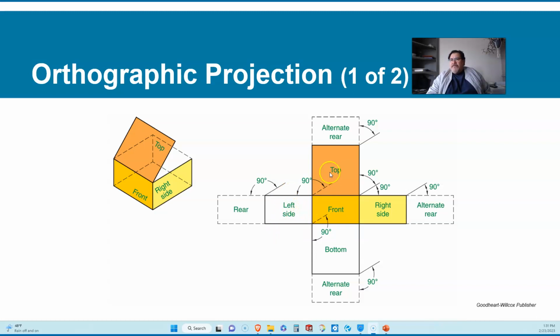When I'm looking at it from the top down, I'm looking at a plan. When I am looking at it from the bottom up, they call that a reverse plan. Because sometimes I might be imagining what the ceiling looks like if I were looking up. And they call that reverse ceiling plans. And those are usually for electric light fixtures.